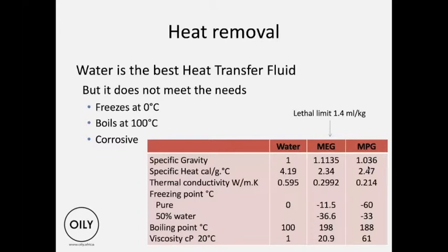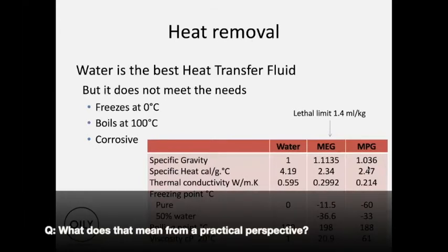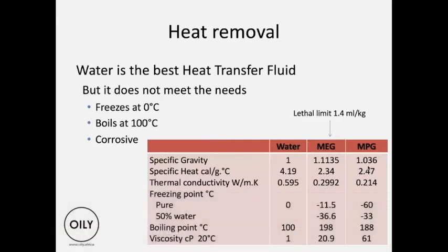Okay. So 1 gram of water going past will take 4 calories away. The glycol, 1 gram, will only take 2 calories away. And what does that mean practically then in terms of coolant? It means that the water is a much more efficient heat transfer medium than glycol. So if you're putting glycol in the system, you need a slightly bigger system. That's all it means. But glycol gives you all the other properties.